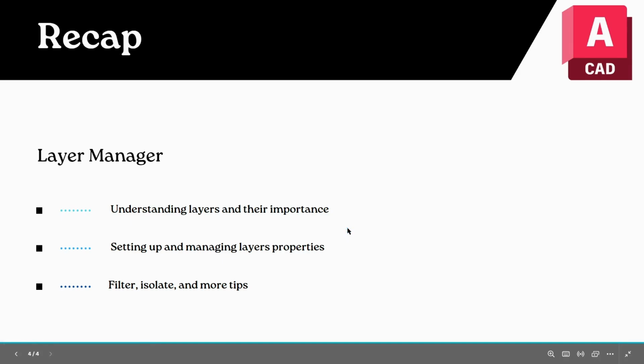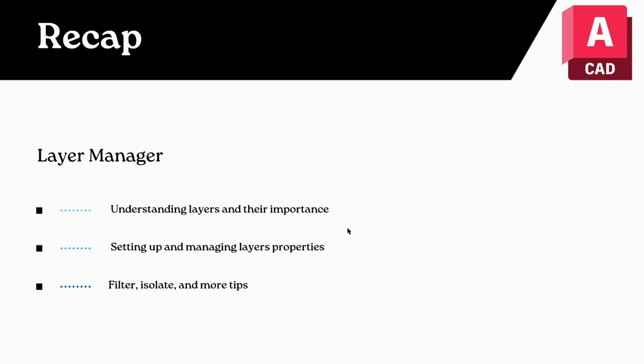Fantastic. So just to recap, in this video, we discussed the Layer Manager, talked about the layers, the different headings and their importance in terms of visibility, how you organize and structure your AutoCAD drawing. We talked about colors, line styles, visibility, and plotting. And we also showed some very helpful tips on how to match your layers, the filtering tools, and being able to search in order to find the layers that you're interested in right away.